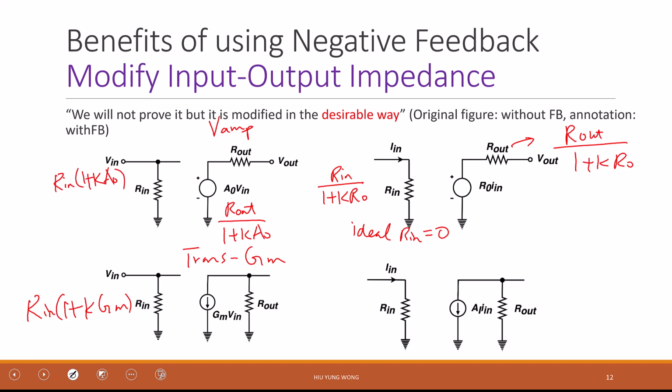So it is larger, right? Why? Because this is a voltage sensor, so you want to have a large input impedance. Desirable means make it larger. I'm trying to help you memorize. This is not logic, not because I want it to be larger, then it becomes larger. Remember this. But we can prove that this is true, and it is in the textbook.